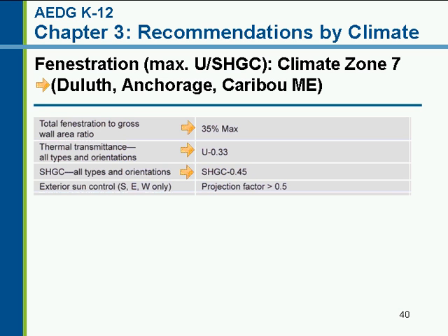But as you're thinking about commercial buildings, sometimes people only envision what happens during the day, and they think, oh, there's lots of cooling going on because I've got the people there, the lights and equipment, and so cooling is really the concern. So do I really need so much insulation? And the fact is these commercial buildings tend to have a bimodal operation. So during the daytime, when they're occupied, let me just say from 8 to 5, the sun's out, people are there, lights and equipment are on, and so it's cooling, that's true.